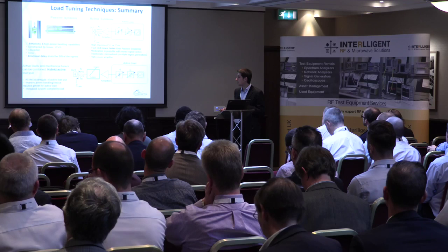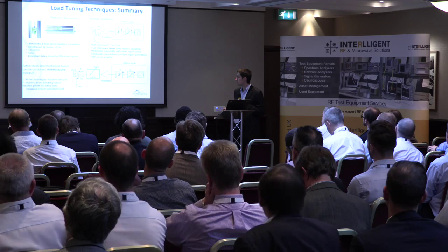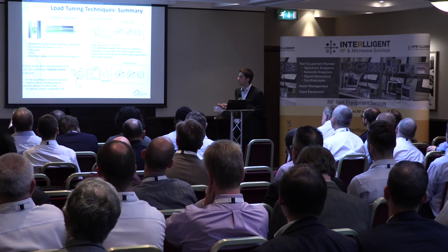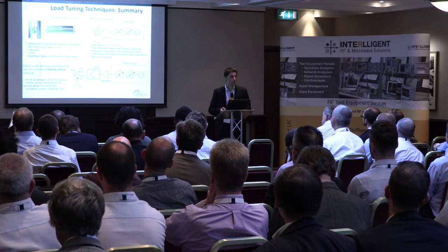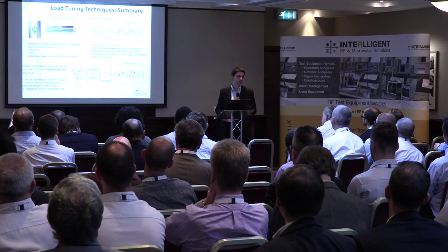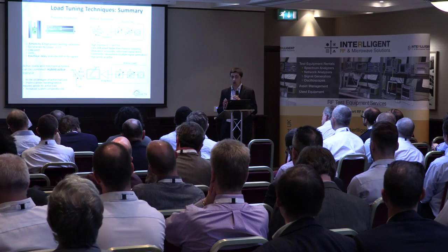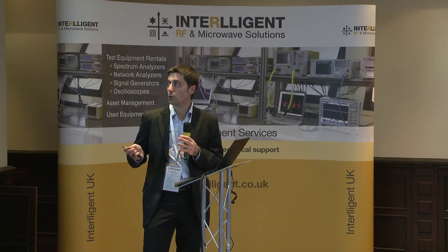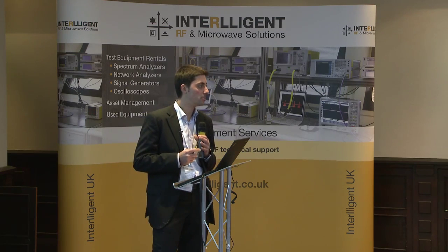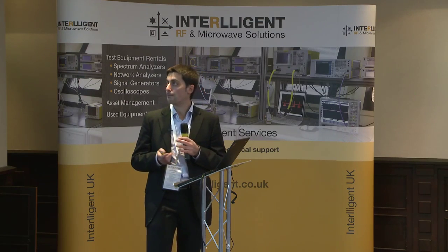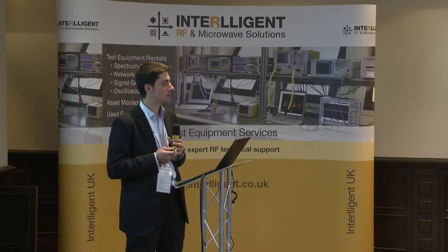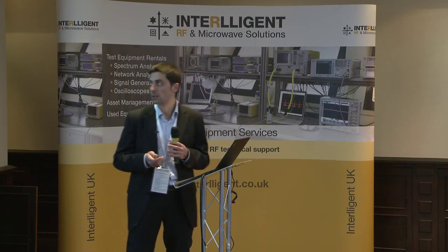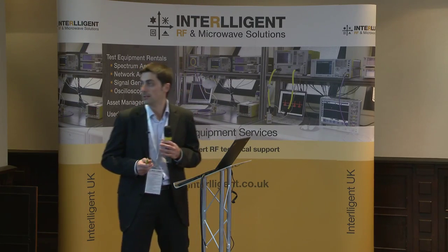And probably the biggest drawback, at least in my opinion, is the fact that you need a big high power amplifier when you want to characterize extremely high power transistors. So just to give a rough rule of thumb, you normally need an amplifier that's at least 2 times bigger than the output power of your device under test. Nevertheless, we have been using these systems up to 500 watt pulsed. It's just that you need a very big amplifier.